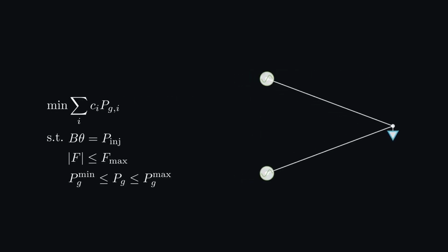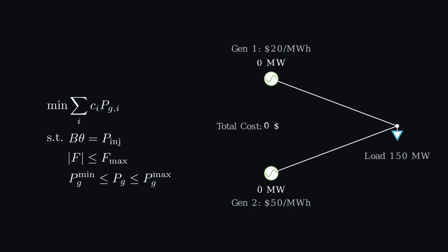Each generator is assigned a linear cost term with respect to active power, and the solver finds the generation schedule, which means total demand, at minimum cost while keeping line and generator limits within range. In transmission networks, where voltage magnitudes stay nominal and lines are predominantly inductive, this formulation provides a fast and practical approximation of the economic dispatch.